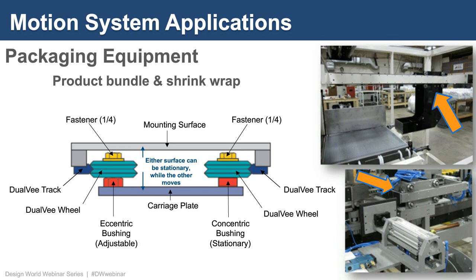And so by attaching these to the machine frame, these linear bearings or guide wheels can provide smooth guided motion along a straight axis. And because they're component-based, like an individual component kit, they can be attached or mounted where needed, and then it's very flexible for how they can be used. In the case of this packaging machine builder, they like the idea and the concept, and they've applied it to many different axes of motion within that same machine frame.